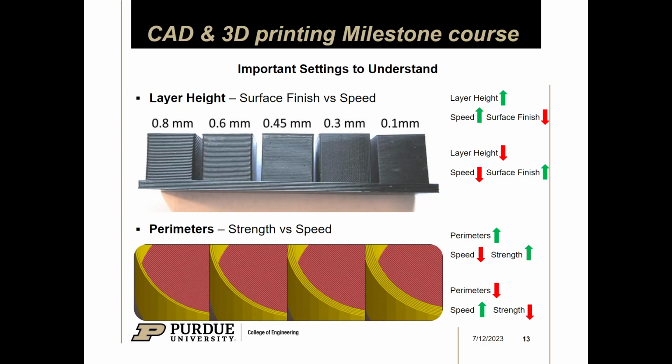Because for a 3D printer like this, it just has a single nozzle and it draws a bunch of 2D profiles of your part and then it moves up every time it finishes a layer, right? So what a slicer does, as the name says, it will slice your part many times to create 2D profiles to make your part, right? So you can change the resolution and you can make it look nice or you can make it print fast, right? So you see there are drawbacks to all of these.